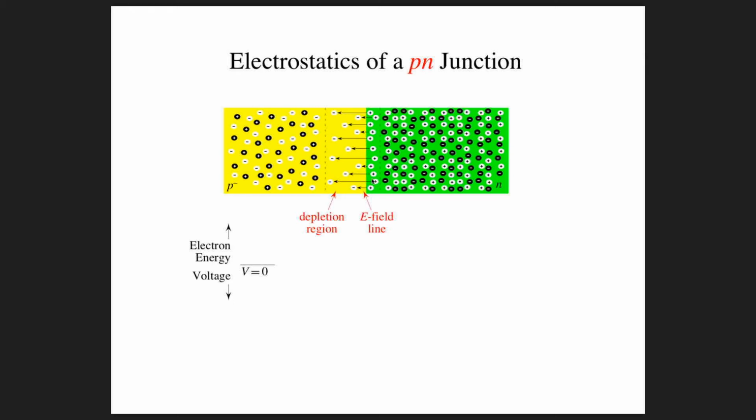It's also called a space charge layer, and that's because this is a layer that has basically space charges exposed. So I'll usually be calling it a depletion region, but you'll sometimes see it called a space charge layer, or SCL. And so this electric field that's set up actually tends to oppose the motion of the carriers due to diffusion,